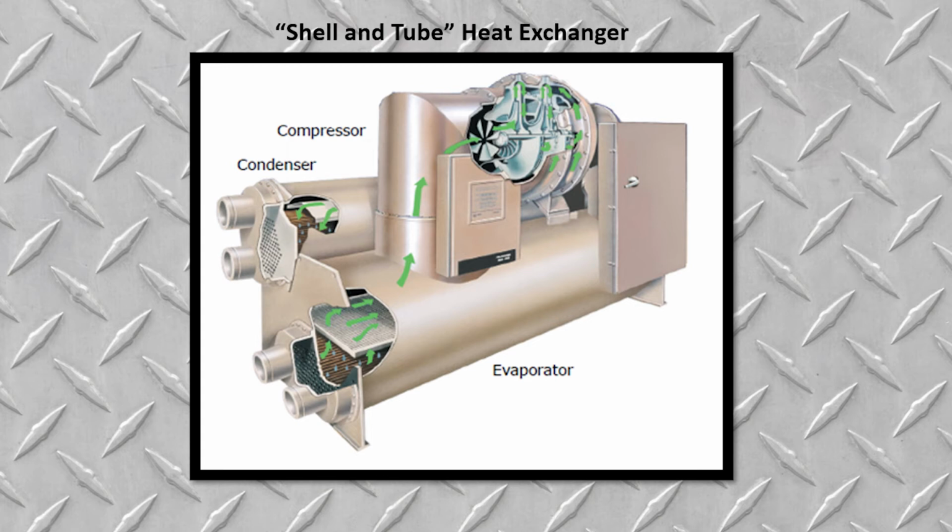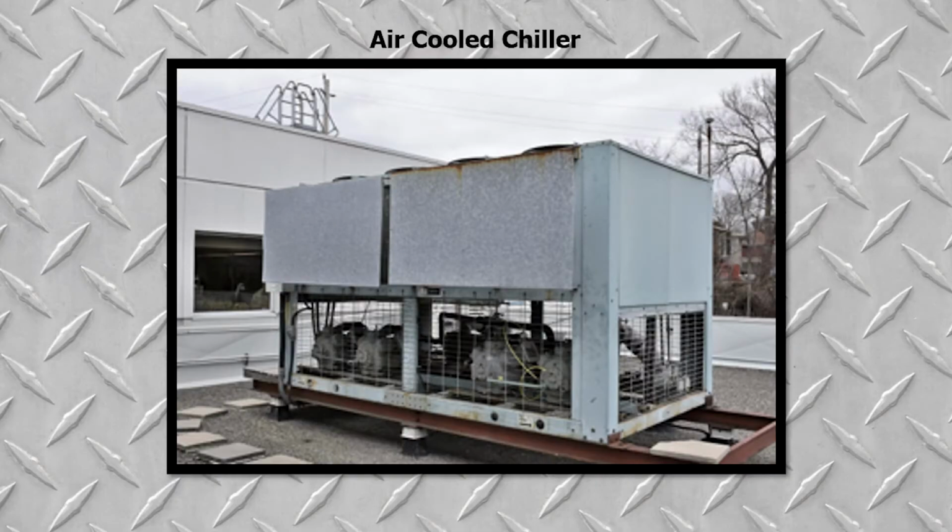Shell and tube heat exchangers are very good for phase change. And what you know from our previous slides here is that there are phase changes in both the condenser and the evaporator. Now, in some cases, either because of space constraints or some retrofit applications like a computer system, you may not put in a wet cooling tower, but rather a self-contained air-cooled chiller, such as the one shown here. This could be done in case water is expensive, limited, or more likely unclean.